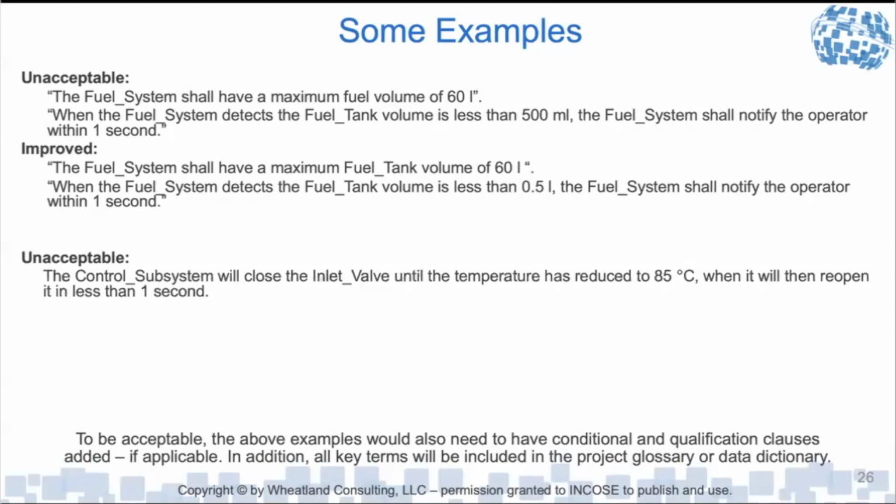Control system shall close the inlet valve until the temperature has reduced to 85 degrees, when it will reopen in less than 1 second. So you can see there's really two actions involved with one shall statement. And in fact, this is actually bad because it had a will and it's not using shall. It's stated as a statement of fact, but if it's really a requirement, we'd want this to be a shall